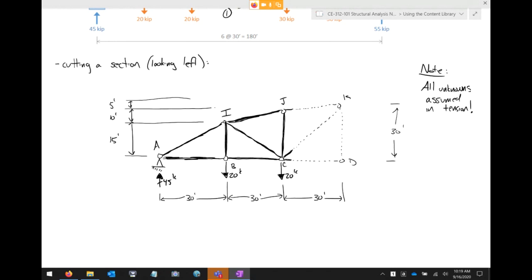Now, question is, were we not required to draw the trusses on previous homework assignments where we did method of sections? Well, yeah, but that's the point. You draw it for the initial problem, but then you have to draw it again where you're cutting a section. I guess you don't necessarily have to redraw it, but I've always felt that in order to do a method of sections correctly and try and reduce the amount of errors, redrawing it ends up being a good practice. So it just tends to be a bit more work intensive for your pencil. So yeah, if y'all have any questions, please throw them out.